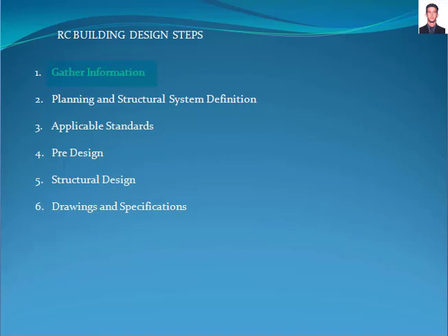Also, this information will help us to choose the proper type of foundation to use, and is important data for seismic analysis. Sanitary facilities data will collect the possible sanitary connection points with the main clean water pipeline system and the main sewer pipeline system. The electrical data will give us the possible points of connection with an existing power line or if a transformer is required. The mechanical data will give us the dimensions of elevators or special equipment that will help with the disposition of the columns or shear walls.